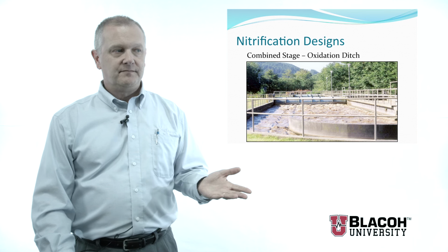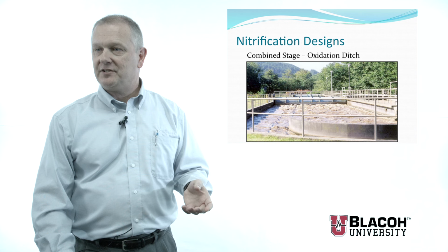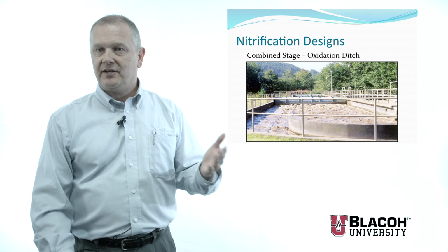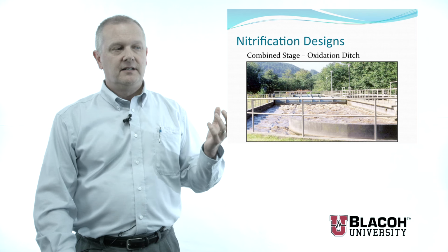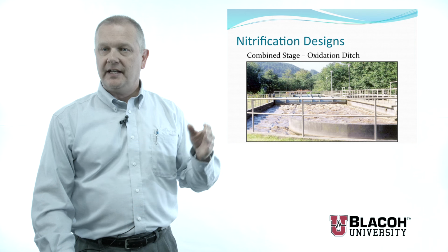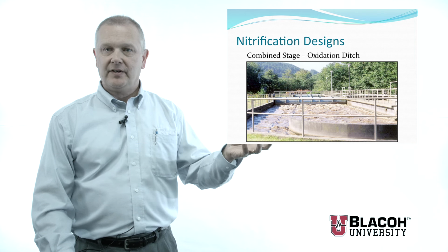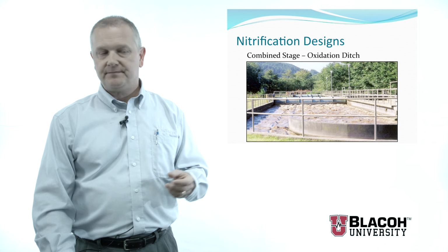Here's an example of a combined stage BOD removal and nitrification system. Most oxidation ditches, like I talked about in the activated sludge class, are designed for both BOD removal and nitrification. And they will remove the organic material as measured by BOD, and they'll remove the ammonia.